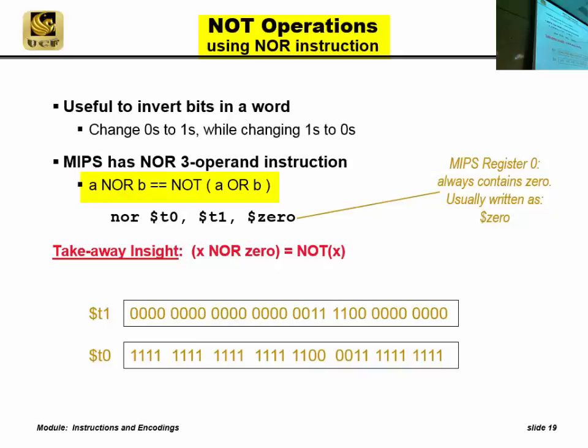If you do the math in Boolean algebra, you see that x NORed with 0 is not x. You'll see for all the cases of 1 and 0, every bit gets flipped. So if this started with a 0, and you NOR it with 0, it becomes a 1. Any 1 NORed with 0 becomes a 0. It has a NOT function.